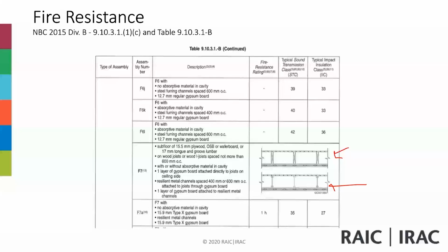So if I'm looking at that assembly F7, F7A, what kind of fire resistance rating does it give me? F7A, floor assembly, 1 hour, thank you.